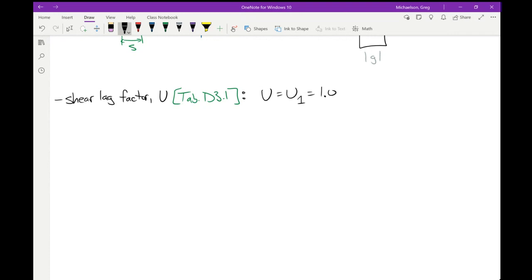But in this instance, because all of the cross-sectional elements are connected, we can go ahead and take case 1 to be the one that applies. If it was only one leg, case 2, because case 2 applies when only some of the cross-sectional elements are connected. So really, case 1 and case 2 are the ideal ones that you're going to want to refer to first. So now what we can do is assess our limit states.